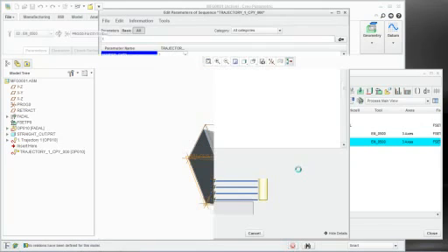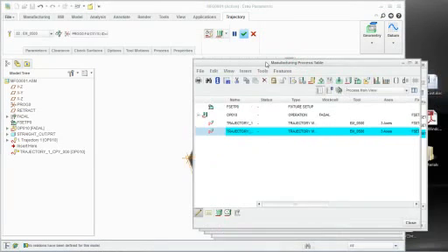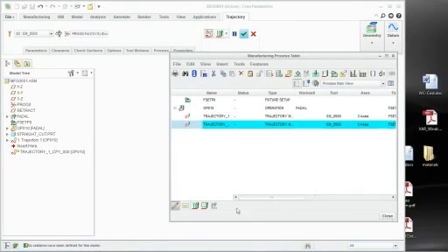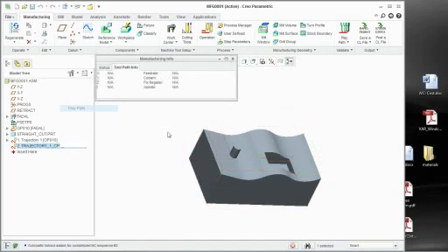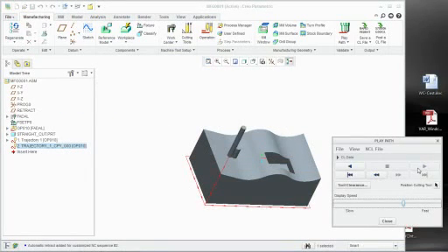And what I've done is copied and pasted that toolpath. There we are. Say OK. There we are. And now, when I play this toolpath, all I did was a copy and paste. I didn't have to pick anything. I didn't have to set up my parameters or my tools. I didn't have to repick geometry. I just did a copy and paste, changed the one parameter that I want to, and then I was able to create that toolpath. Now, the trajectories actually work well for Control-C and Control-V.